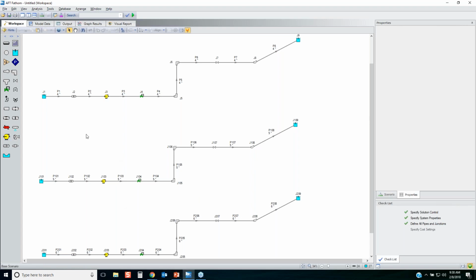Okay, next thing I want to do is set up my goal seeking control module so I can figure out what my tank heights need to be. Imagine, if you will, if I had to run this model and individually change each of these supply tanks by themselves and constantly go through a guess and check process to ensure that the suction pressure at each of these pumps for each of the systems equaled 2 psig.